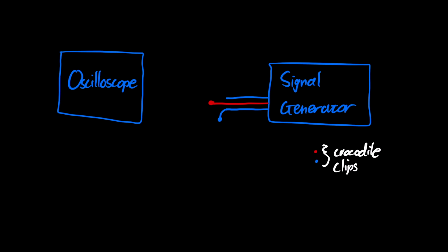One end of a coaxial cable with a poor transfer impedance is then connected to the input channel of the oscilloscope. This cable is referred to as the cable under test. At the other end of this cable, the return conductor and the center conductor are soldered together.